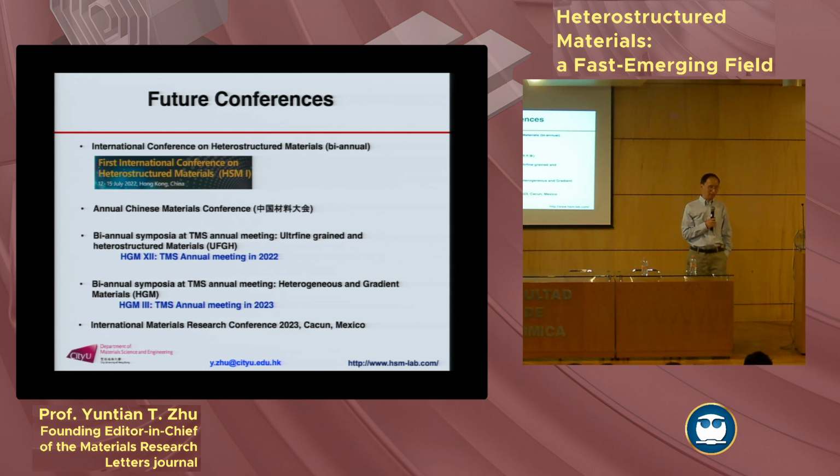But when you look at the silver alloy, do you know that it consists of two phases? Yeah, they got one hard phase, like a fiber, and the other one is the matrix. So actually it is a heterostructure, in my opinion. There's someone in CTU who tried to see how this concept works for high temperature alloys. He found that the heterostructure has a much higher fracture toughness. With the heterostructure, you got one phase that is tougher. But if you have a fine-grained one, that doesn't work, of course. You need a different heterostructure.